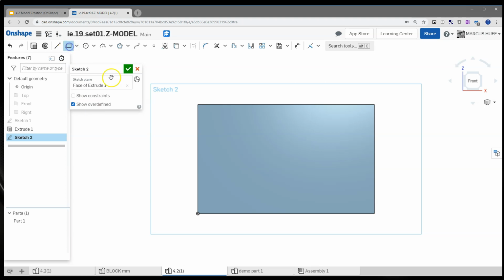Choose the 2-point rectangle, select the corner, drag it down, click, and we're going to put 1, enter, and 1 and enter. And what that does is it makes it go ahead and that's the one I wanted to escape, Control Z.